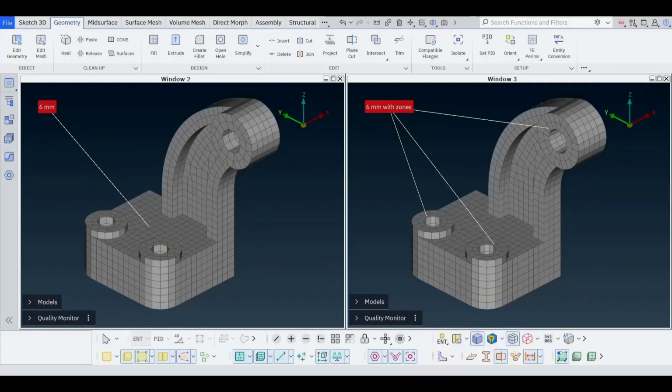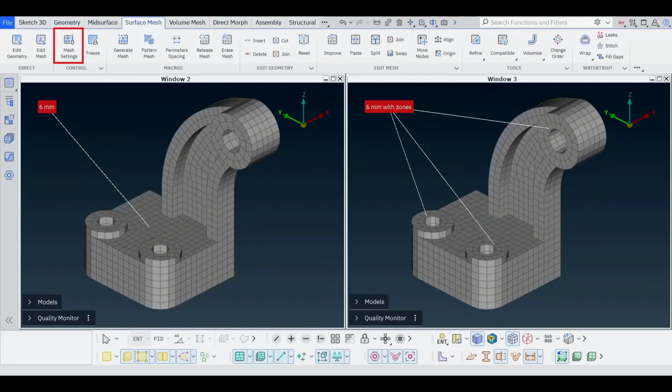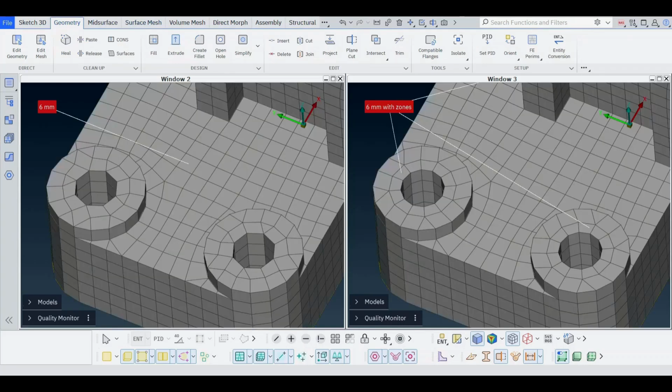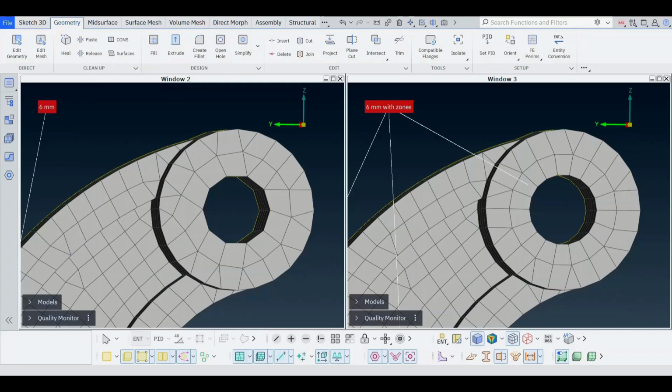For example, in the second part, since the 3D holes recognition feature is enabled, and the setup for 3D hole treatments is activated, zones can be generated. 3D hole treatments activation can be set either directly in the global settings, or in the meshing scenario, and the scenario then copied to the global settings. Around the holes, zones of a defined width of 4 and 6 mm are created, improving the mesh flow.